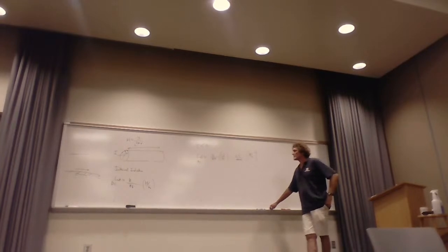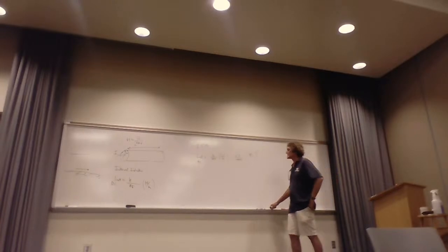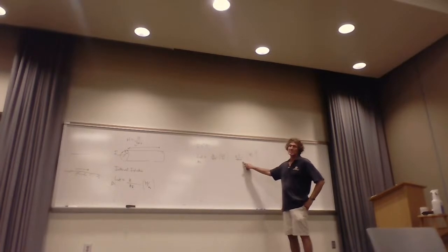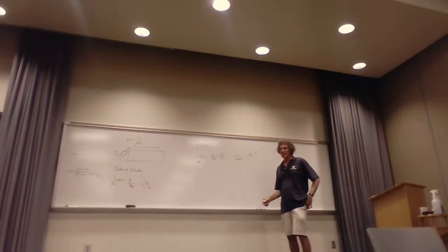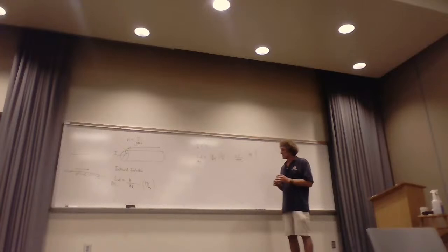Something to be said about this: the internal inductance will tend to be just about 0 at high frequencies because the skin depth gets so small, you don't even worry about it. But the external inductance will always be something you have to consider because it always has to do with the return path. I am just about out of time here, so now I'm going to finish my story.